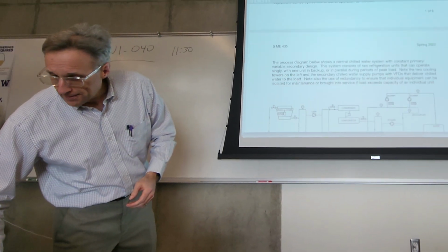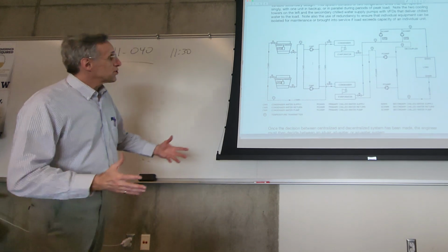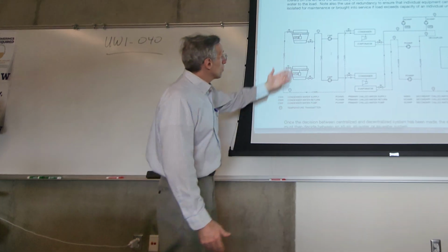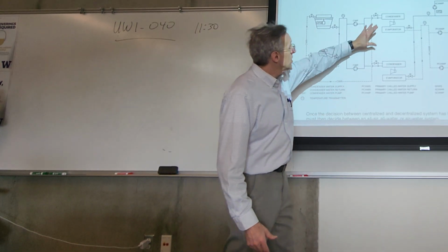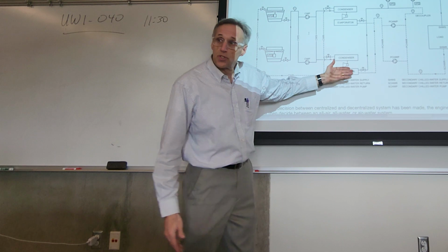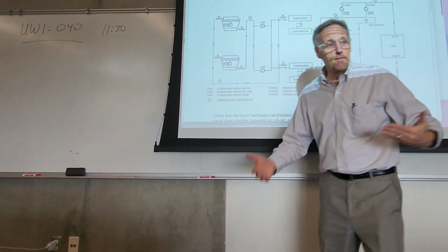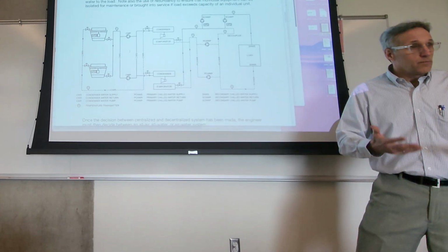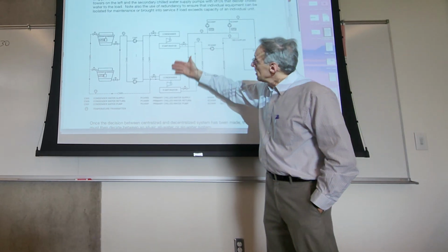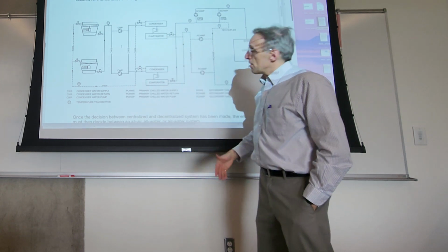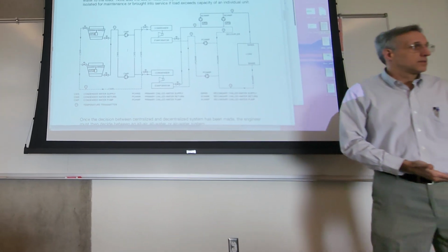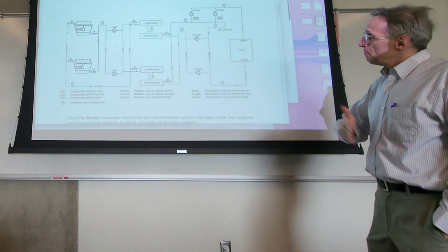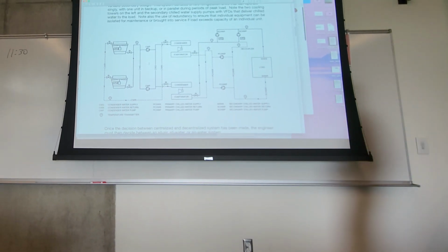And there's just some discussion here of what these look like. So here is the central system. Our cooling towers are over here. Our chiller. Here we have two chilled water systems. Usually there's more than one because you have one that serves as a backup, where it can be brought in when the load is especially heavy. You can kick in and use both. I think here we have 3 or 4. There's quite a number of them, and they stage them based on what the load is.